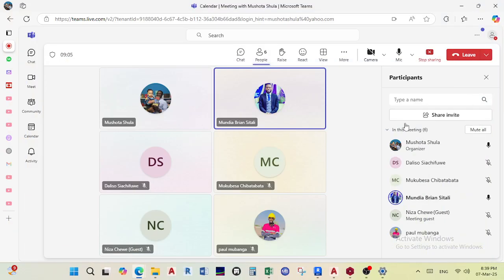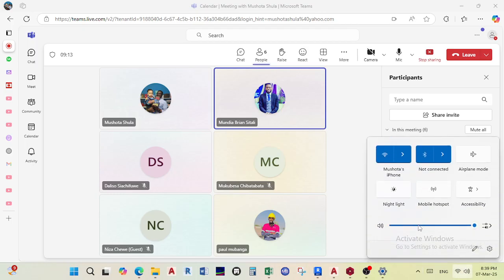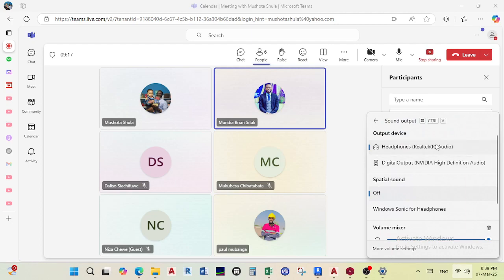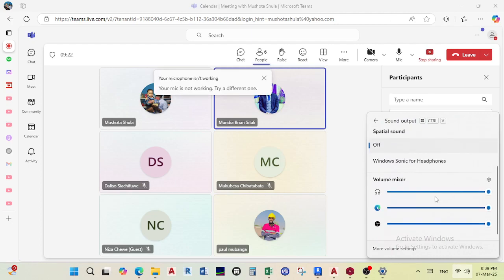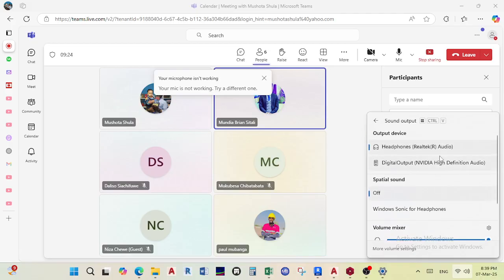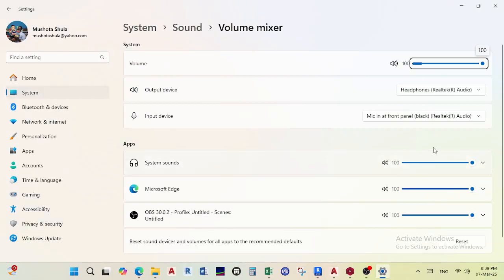You can't go 233 meters just pouring, pouring, pouring. You're going to have a probability of having some cold joints somewhere. So you want to terminate structures. Like you and I were at the King's Hospital. You know how that King's Hospital had like 25 meters max. You have to have a construction joint.